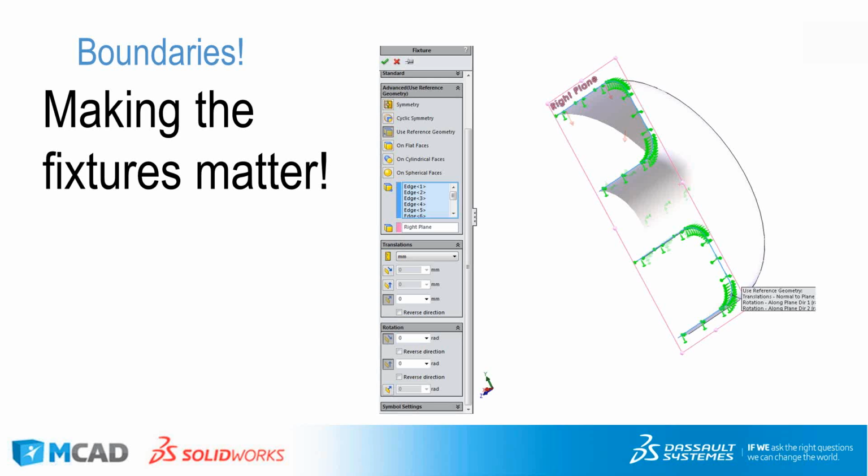And in reality, some things aren't a true rigid connection like that. There's a little bit of deformation, but not to the same degree. So we can come in and start using things like reference geometry to specifically constrain the degrees of freedom that we want without having to come in and just use fixtures everywhere. So you can see on this one, I've grabbed the edges where it defined my shell for that guy.